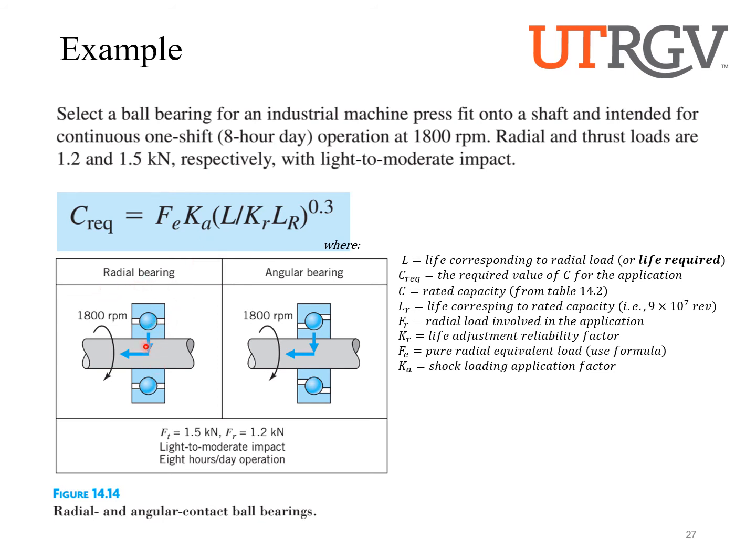And remember, ball bearings, we can get them as radial bearings, which are designed just to take radial loads, and angular bearings, which are designed or better equipped to take thrust loads. You can see the internals a little bit, just roughly the geometry. We have a big shoulder on one side and a very small shoulder on the other. So this one can take the lateral forces, and you can see the resultant of the two forces in this direction, radial plus thrust. Anyways, the angular is designed to take thrust loads better. So in this example, we're actually going to spec radial bearings and angular bearings.